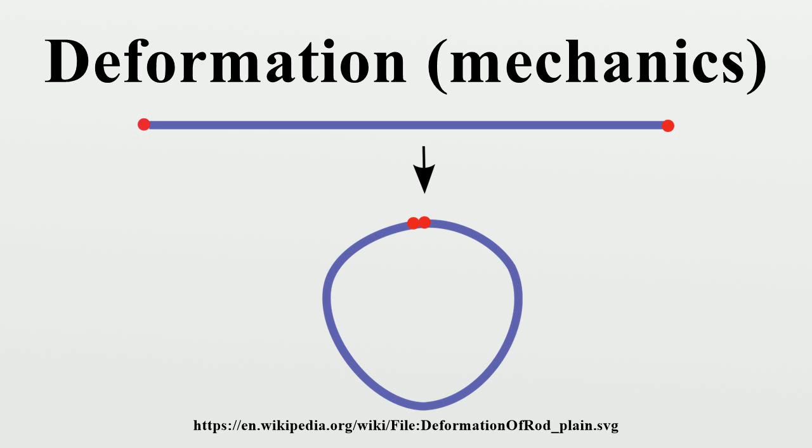The true shear strain is defined as the change in the angle between two material line elements initially perpendicular to each other in the undeformed or initial configuration. The engineering shear strain is defined as the tangent of that angle, and is equal to the length of deformation at its maximum divided by the perpendicular length in the plane of force application, which sometimes makes it easier to calculate.